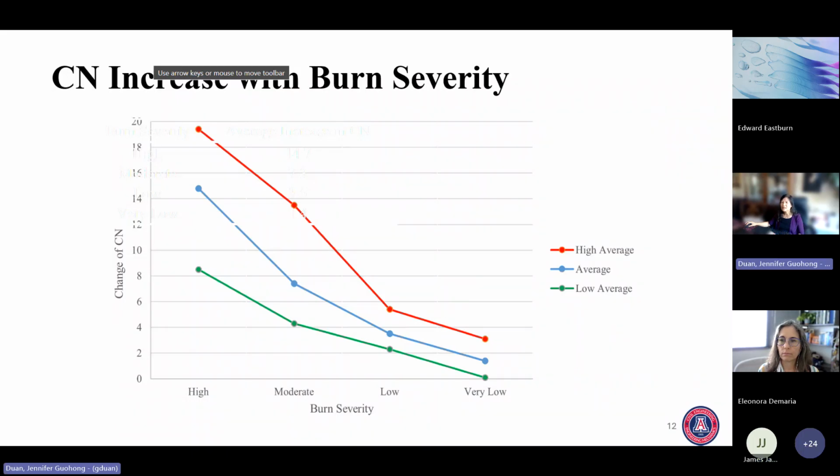Yes. So this is a curve number immediately after the burn. We use 30 to 45 days. We're using a vegetation reduction map. So after the burn, they tell you this 30 meter by 30 meter area, 90% of trees all burned. The satellite image shows the vegetation is all gone. So this is high burn severity.